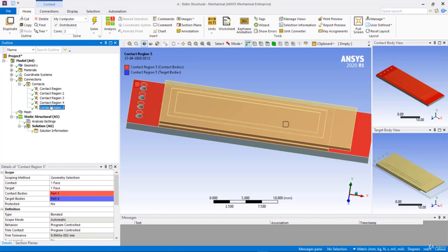So what Ansys Workbench does is, when you take in an assembly or a body containing multiple parts, it will automatically try to detect the contacts, and it will automatically generate them using the inbuilt algorithm inside the software. And most often the automatic contacts that have been created are good enough for medium complex objects, as well as some complicated assemblies. It can very accurately generate the contact regions by itself automatically.